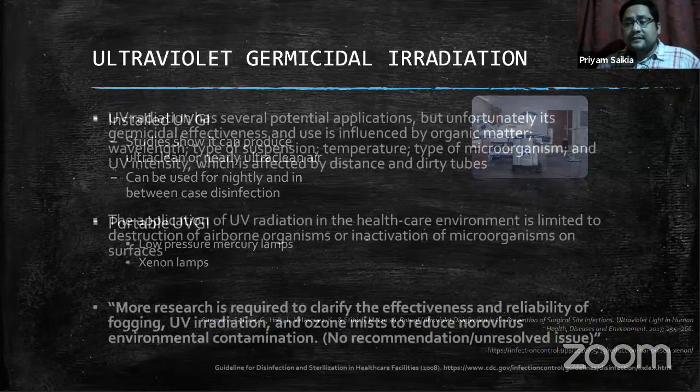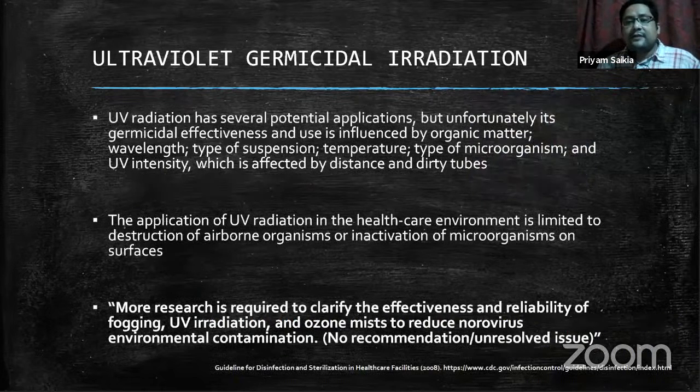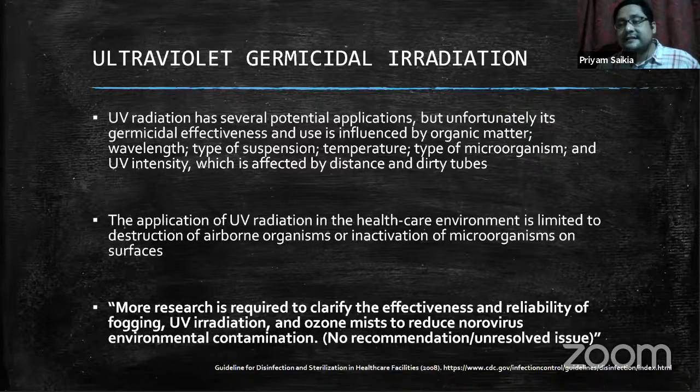Ultraviolet radiation, though it seems very attractive, has several potential applications, but unfortunately its domiciliary effectiveness and use is influenced by the presence of organic matter, the wavelength being used, the type of suspension, temperature, the type of microorganism, and the intensity of UV light, which is affected by the distance. The greater the distance, the less the effectiveness. And with time the tube becomes dirty, and with dirty tubes we are not very sure how much UV radiation is coming out of those tubes.